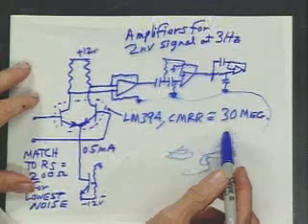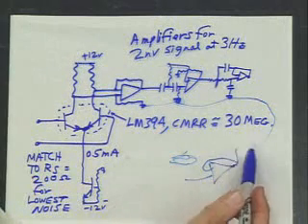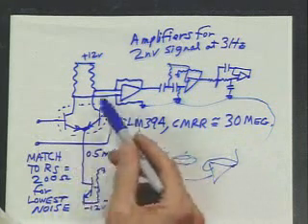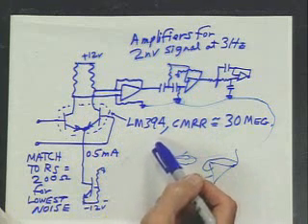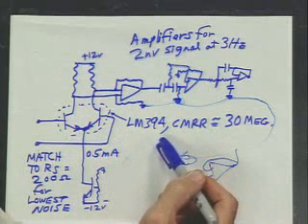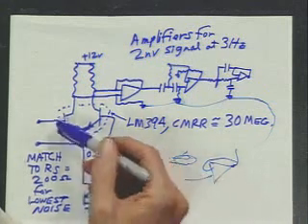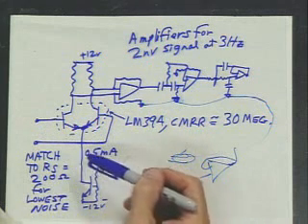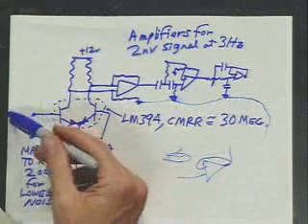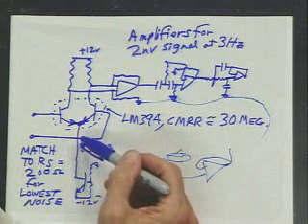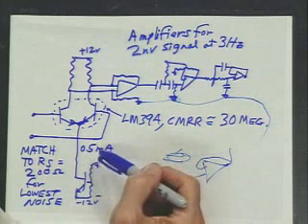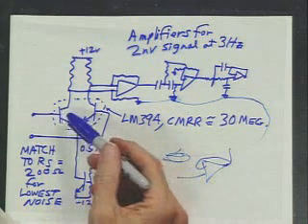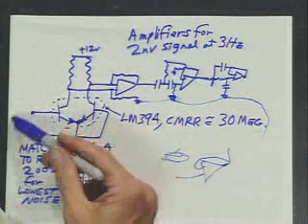The question we have now is, what is the best way to make a low error amplifier? Well, we take the LM394, which has low noise and very low voltage and current errors. What's the voltage noise? Small. What's the current noise? Small. How do we compare the voltage and the current noise times the RS? We choose this 1/2 milliampere of emitter current for both pairs to provide low noise. So the noise is negligible.